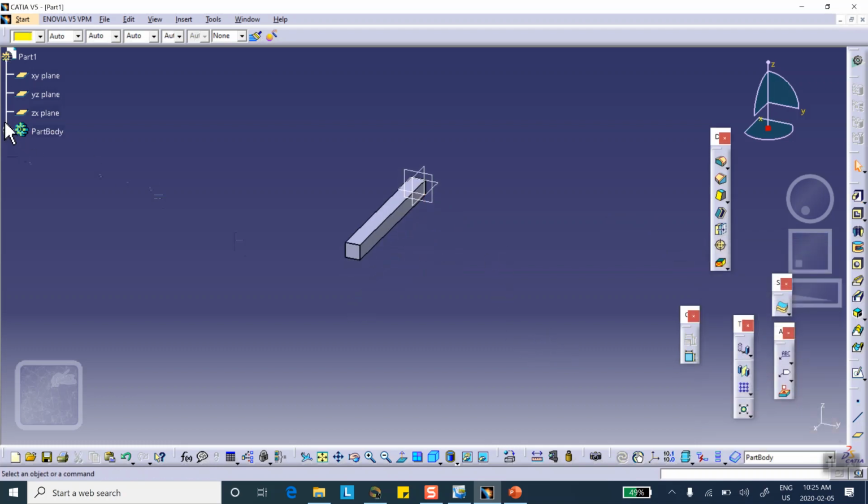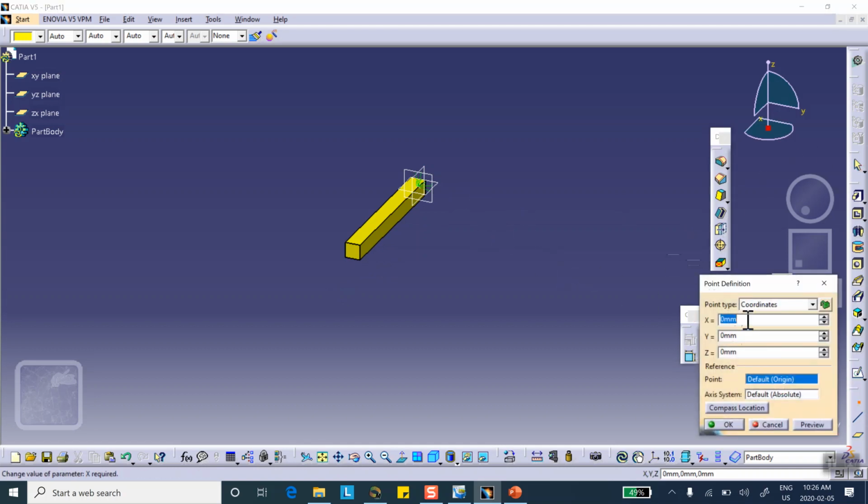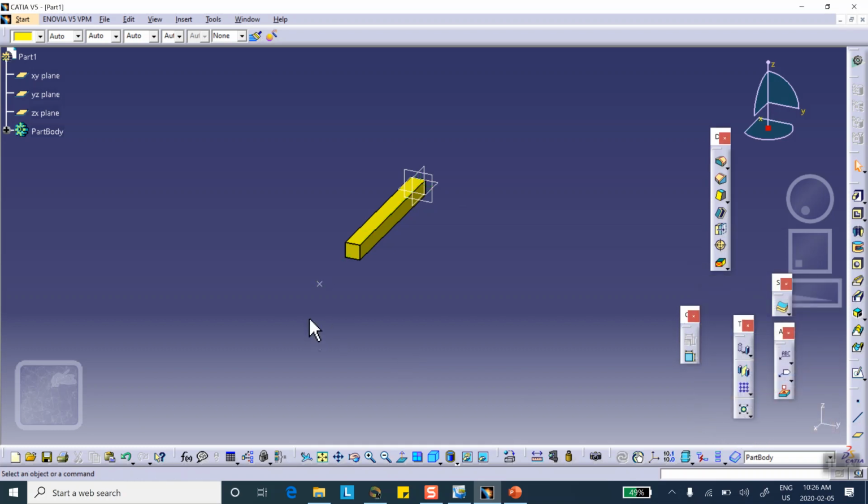Okay, let me make this yellow right there. Now I'm going to create the handler point of the virtual part at 150 millimeter from the clamped end, which is over here, or 50 millimeter from the side. So let me do it from 150 millimeter from the clamped end. 150 there. This is going to be the handler point of the virtual part.